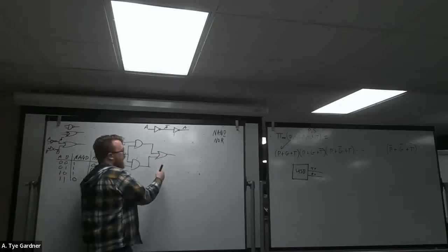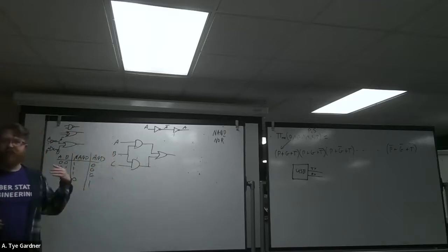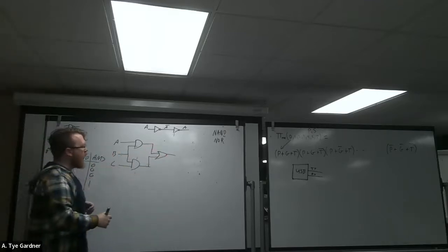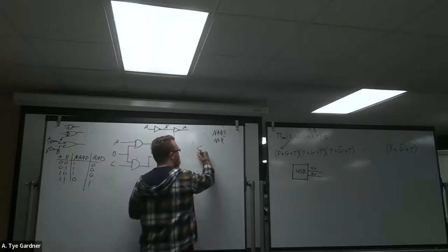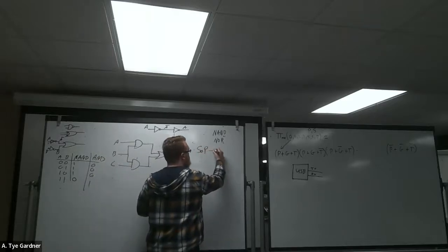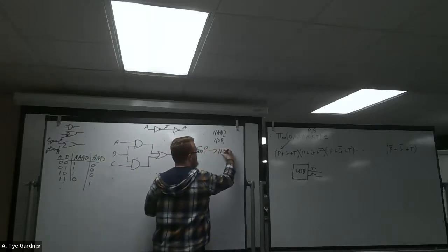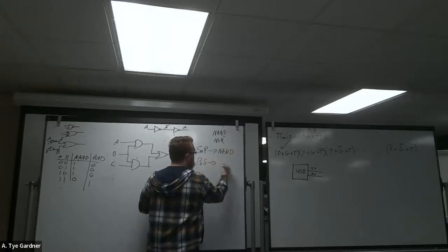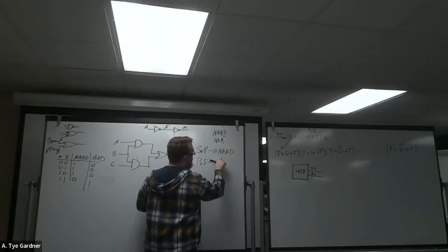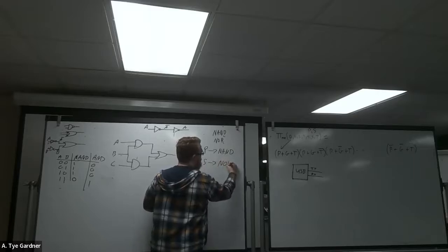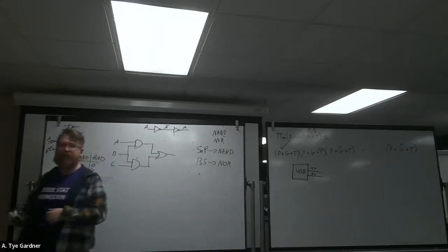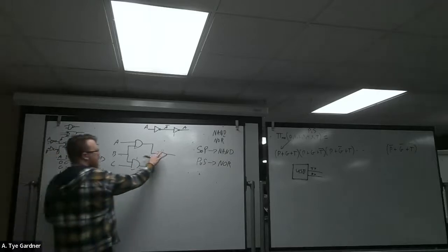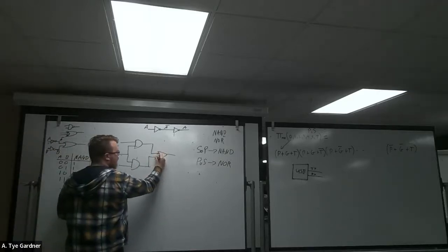What I'm going to do is I like to do this conversion right to left. There's actually a way to do left to right. I find the right to left easier. And when you do right to left, SOP becomes NAND, and product of sum, which I don't abbreviate for obvious reasons, becomes NOR. Okay, that's the rule. What that means is, well, let's put a bubble here, right?